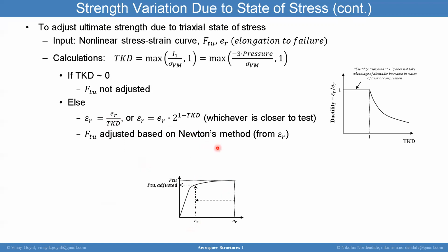As a general note, when you are trying to predict an ultimate margin and your state of stress is above the yield strength, your margin can be different depending on whether you're talking in terms of stress or strain. They're the same when you're below the yield strength. But once you're above it, margin, which is typically a linear projection of capability, differs. So I encourage engineers, if you're predicted to be above the yield stress, to report ultimate margin in terms of both stress and strain. It gives you at least two numbers to get a better feel for where you are.